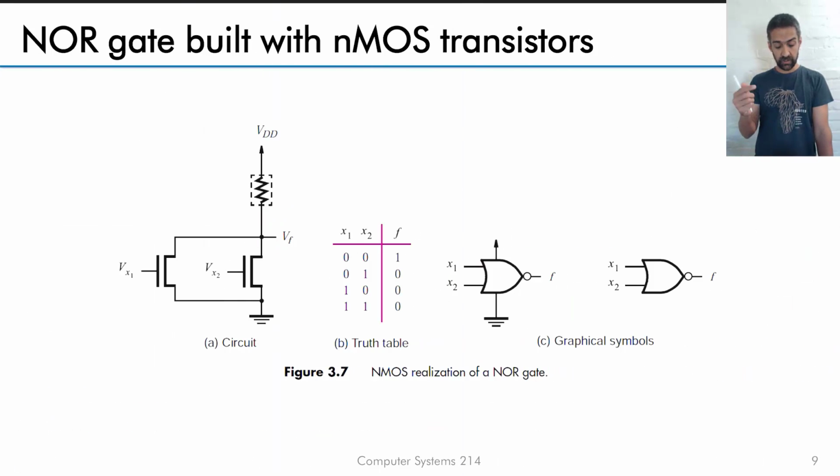And this is why when this is killed, so there's no flow there, then this point here is high because there's almost no current through the resistor, which means the voltage drop across the resistor is equal to 0. And that's why this output F is equal to 1.